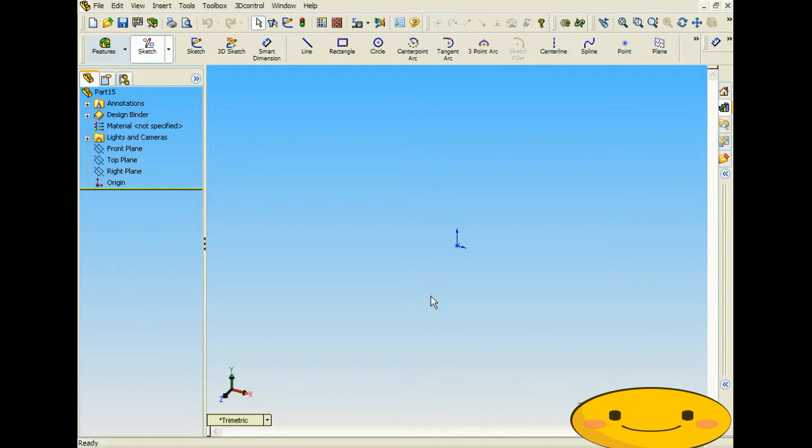So we're going to be covering the traction wheel-on-edge feature, and what this is going to resemble is a wheel and an edge moving together like a rack and pinion. So you'd use this kind of like to mock up a rack and pinion that you're developing, and just to see the motion and how it's going to move together. Again, we're going to be using sketch blocks. So to start off, let's start sketching it out.